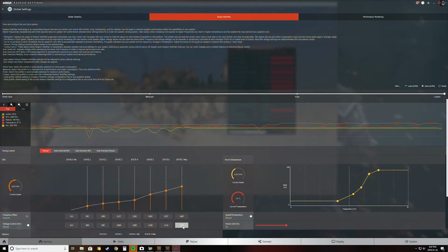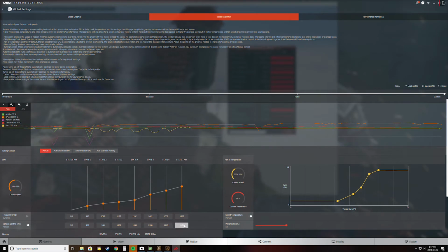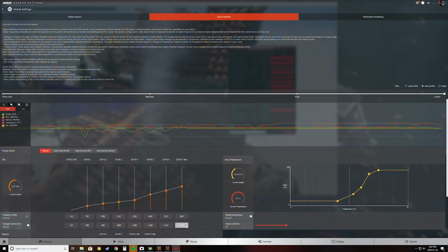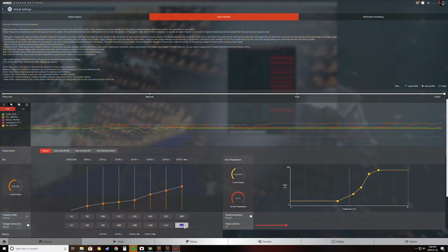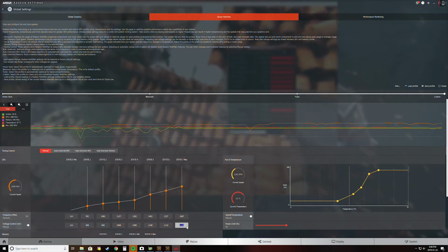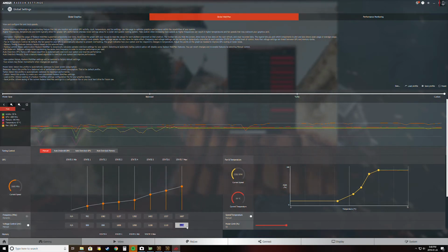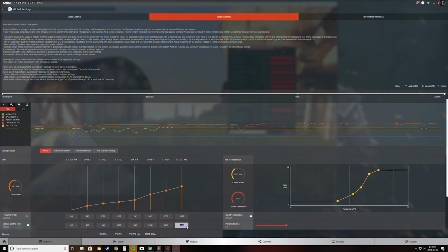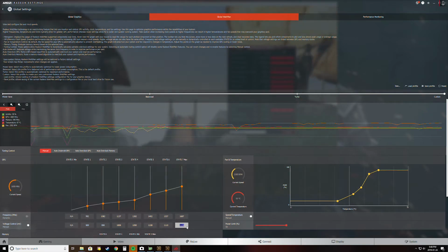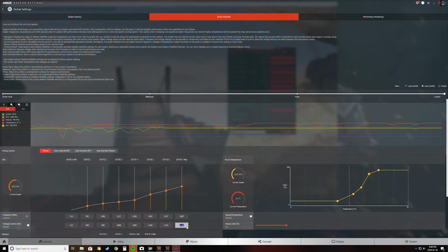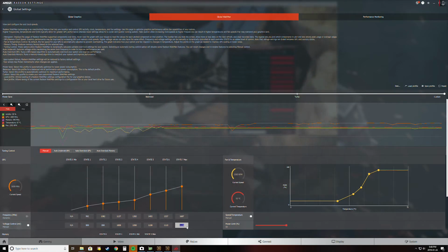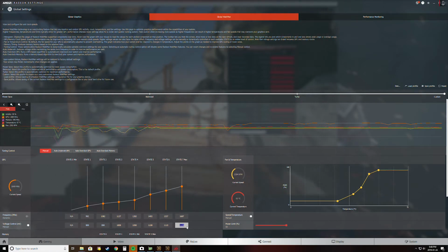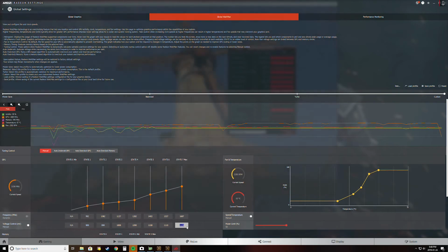Okay, so using that system, either you drop this lower, 1115, maybe 1065 millivolts, then you get a crash at 1687 megahertz. Well, now you need to increase the voltage or lower the clocks.